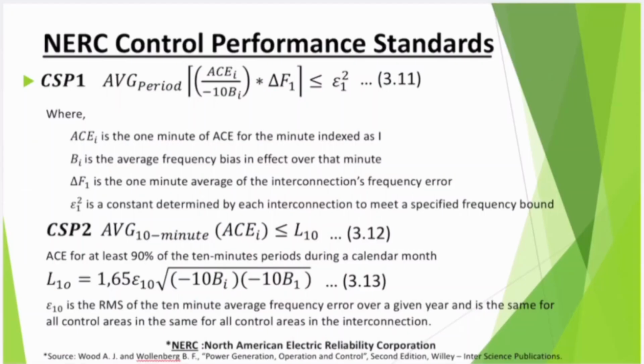When you draw more load through a tie line, your frequency keeps on dropping, and hence you are extracting power from others. So you cannot do that and disturb another system which is controlled through a tie line. We all have to respect our frequency and manage our own load and energy so that the tie line commitment can be met.